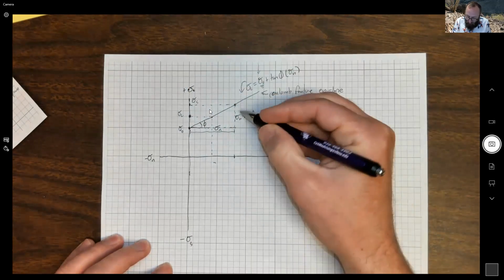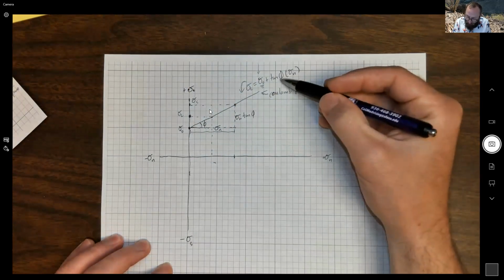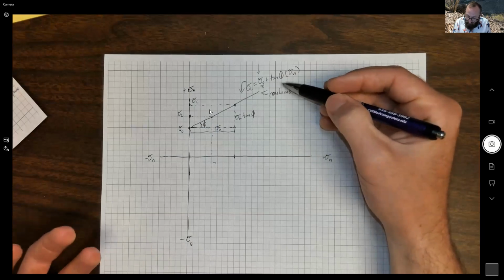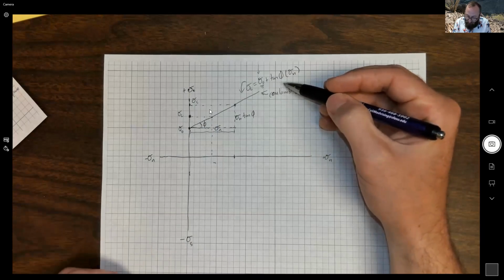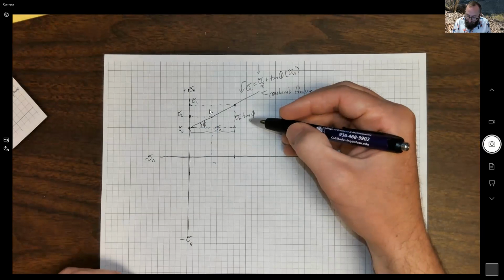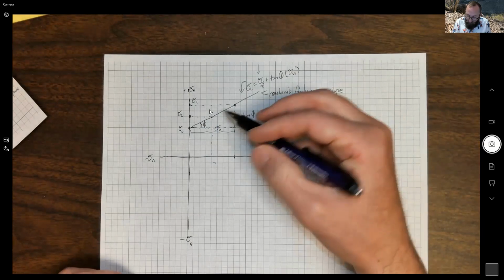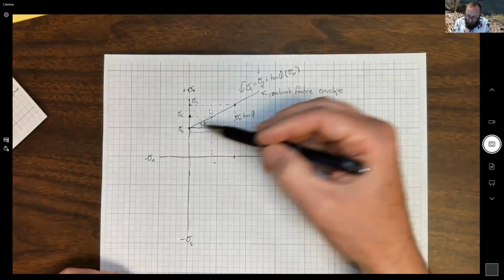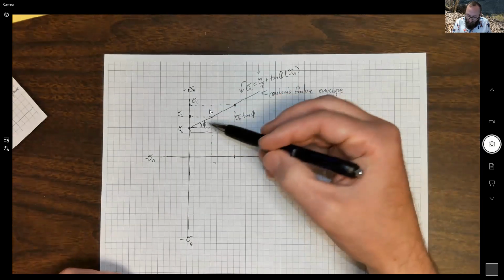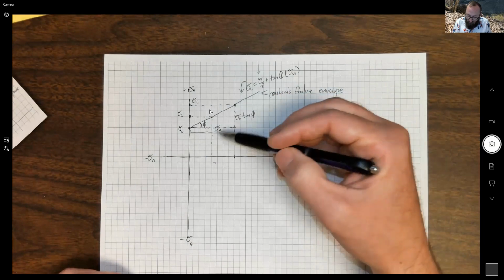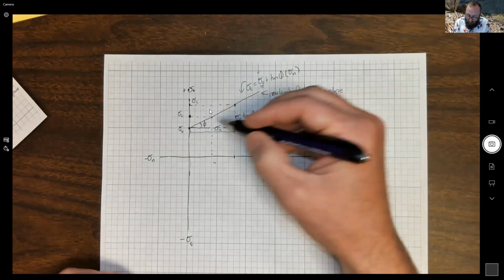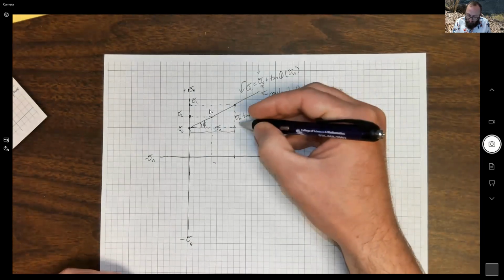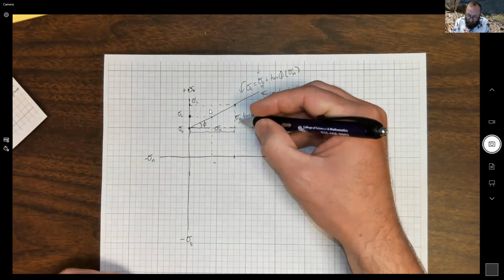So the amount of stress it takes for failure is basically a ratio between the difference between the cohesive strength and the shear stress, and sigma n, which we can express in terms of tangent. Okay, so sigma n tangent phi.